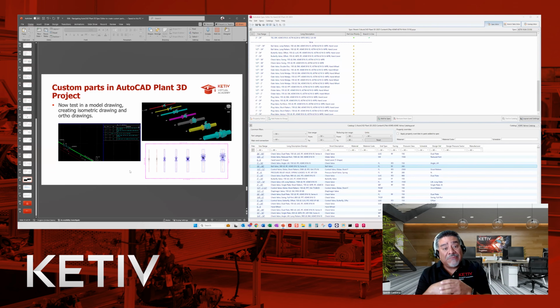And at that point, you definitely want to test it first before having your designers move into using it in production mode. So you would want to place it in model drawings to make sure everything is connecting as you were expecting, and then run your isometrics off of those examples to make sure everything shows up correctly within the isometric drawing itself, and also within the bill of materials.